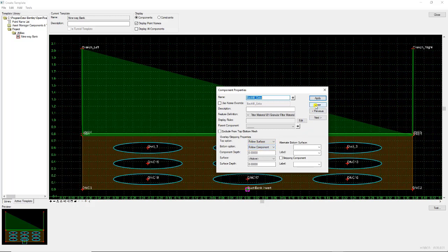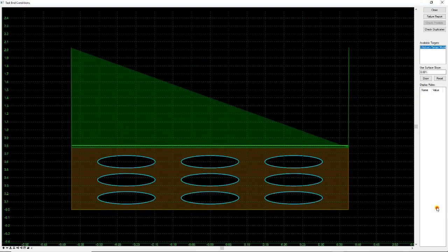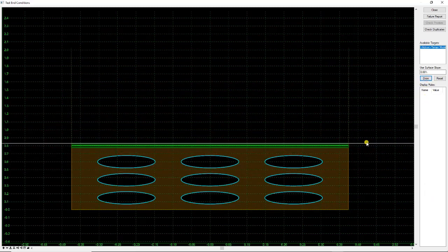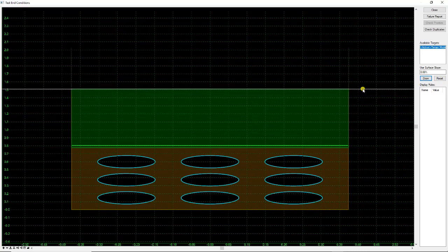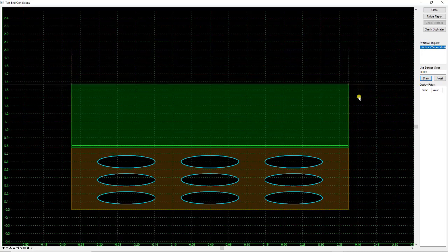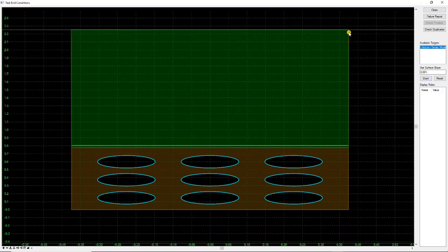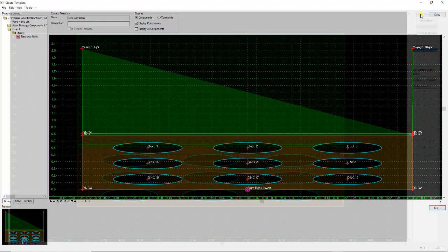Now, how does that work? Well, if I just come in and test this, you can see that we're always displaying the duct bank there, but as the ground gets further into cut, you can see the end conditions are finding daylight with the ground, but with that stripping component, we can get a volume out for our backfill. So again, a useful tool in the template creation.